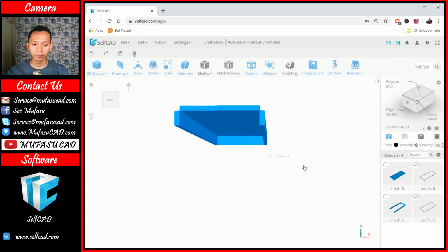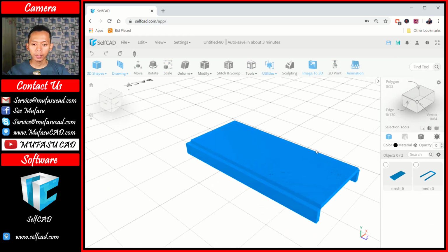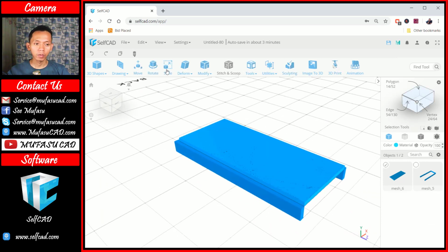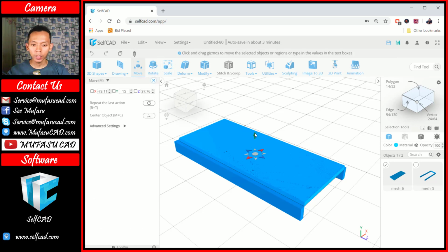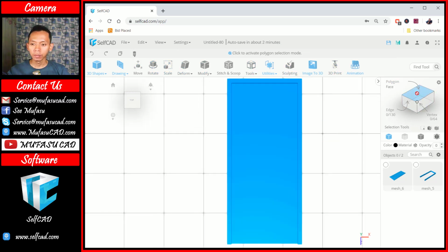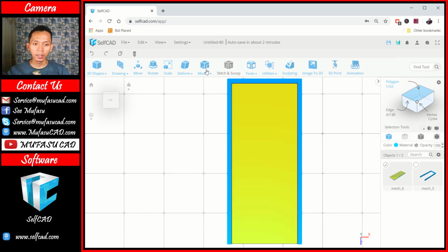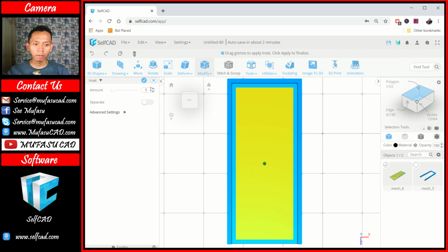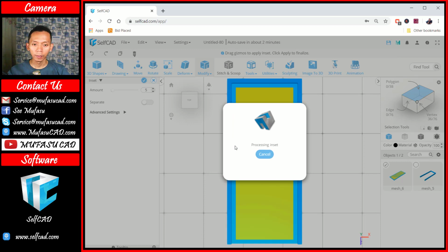Click yes to delete. The next I will select these objects and then you can use move tools. You can click here move. If you move in the green axis, I will move to the bottom here. And the next I will change into top view. In here I will use a polygon option. Okay, you can select these objects and we use a polygon option. Select at this face. And then in here I will use the insert option. We can insert with amount 5. Okay, this is about amount 5 and you can click OK to apply.